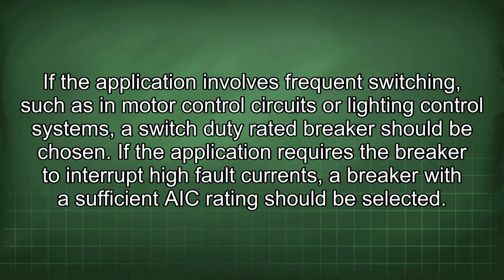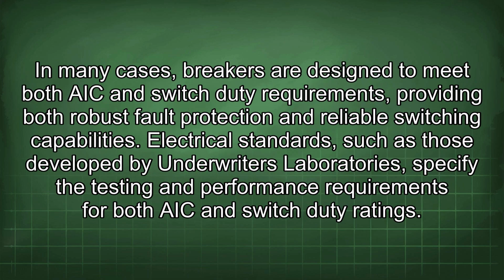If the application involves frequent switching, such as in motor control circuits or lighting control systems, a switch duty rated breaker should be chosen. If the application requires the breaker to interrupt high fault currents, a breaker with a sufficient AIC rating should be selected. In many cases, breakers are designed to meet both AIC and switch duty requirements, providing both robust fault protection and reliable switching capabilities. Electrical standards, such as those developed by Underwriters Laboratories, specify the testing and performance requirements for both AIC and switch duty ratings.